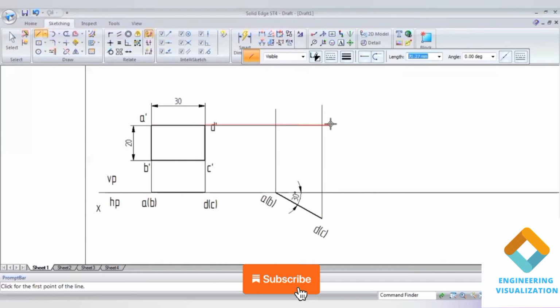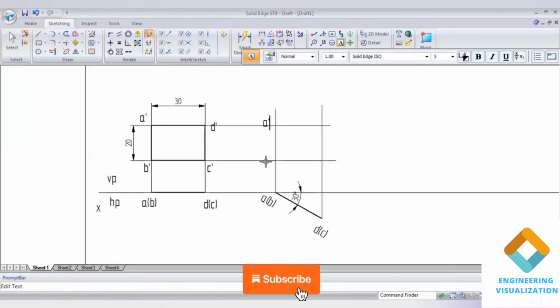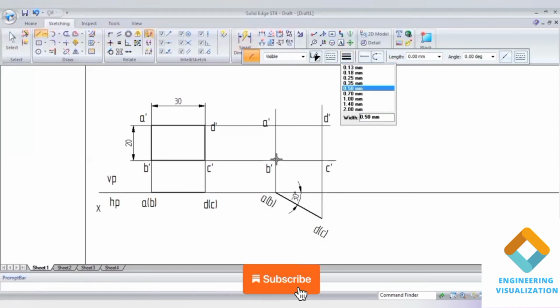Draw the projection lines to complete the second position front view. And write A dash, B dash, C dash and D dash. Go to thick line.